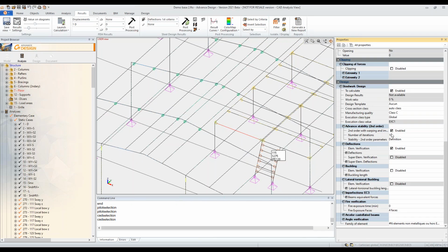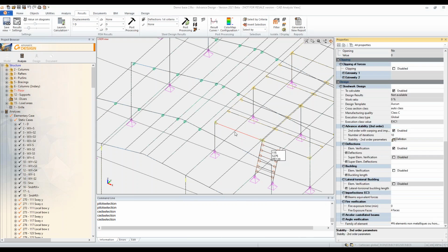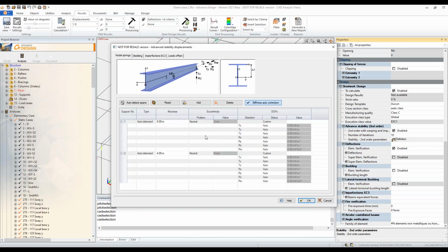This is where you will use it, because this method will isolate the member. The boundary conditions will be turned into a set of nodal springs, you see, and for each edge, you're given access to not 6 but 7 degrees of freedom, because the seventh one is the warping. You know, RW is for warping.